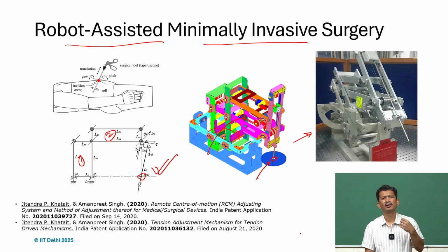It means we may need some mechanism to adjust in the range of maybe 0.1 or 0.2 millimeter and get rid of those tolerances. So that's the importance of compliant mechanisms. And when we study controlling degrees of freedom and constraints, we also understand that the adjustment and alignment requirements are very important if you want to achieve precision.